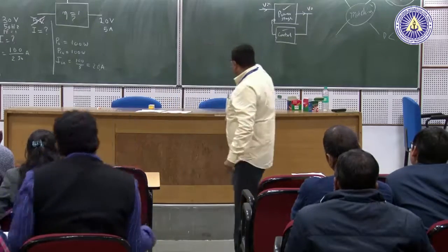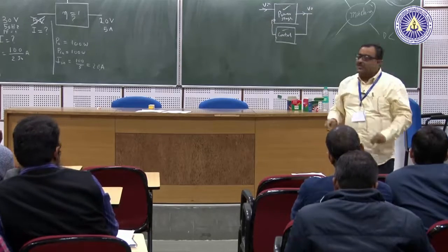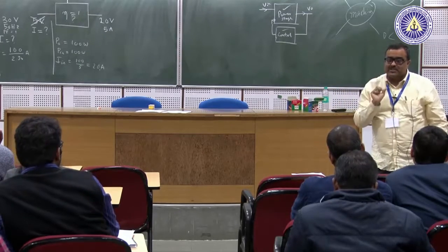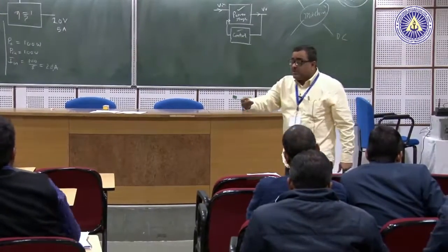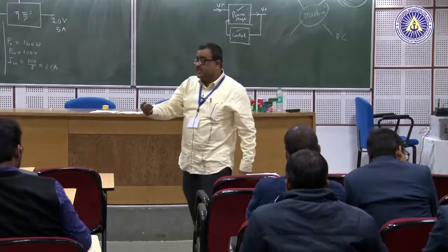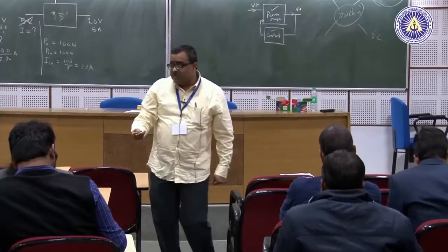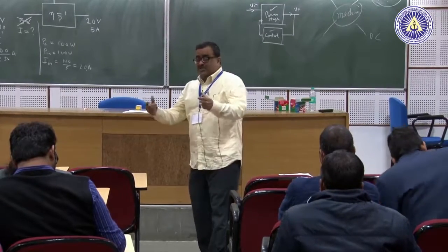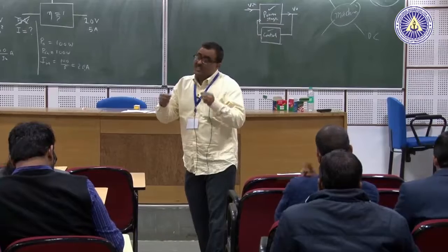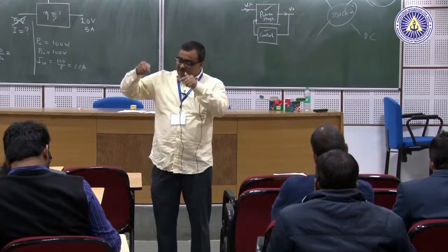So, what I am trying to establish is that in every power electronic converter, there is a power stage and there is a control stage. That has to be taught. What is there in the power stage? MOSFETs, IGBTs, silicon carbide MOSFETs, GaN MOSFETs are there in the power stage. Just a MOSFET, can you drive the MOSFET? No, you need a gate driver. Why do I need a gate driver for that? Then you go one by one.